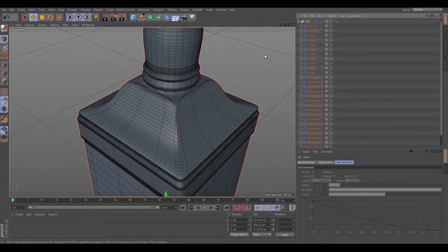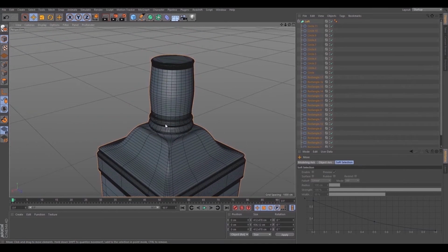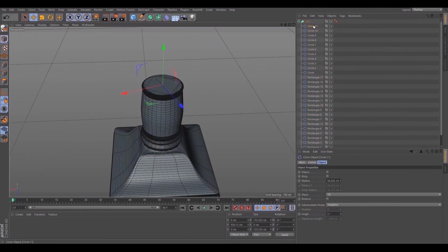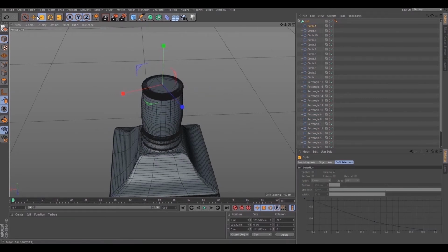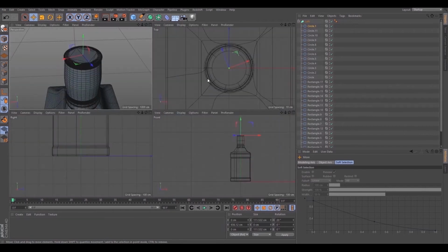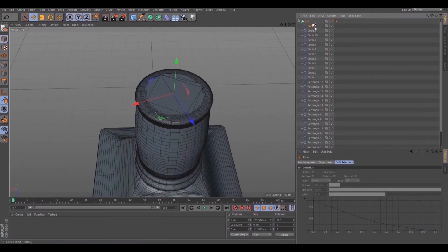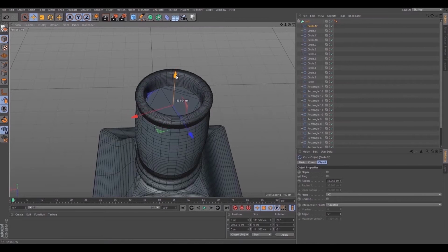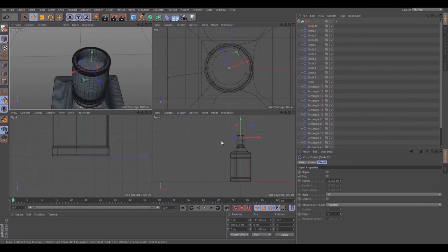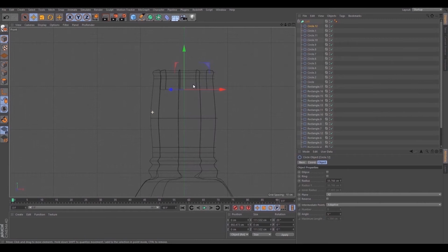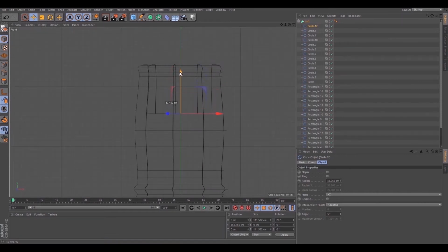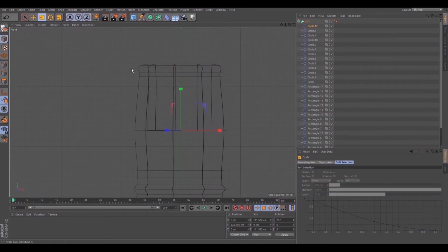Next we need to make the inner shape of the bottle. Copy this circle, scale down to the thickness of glass. New copy and move it down. Then, in front view, adjust the position with circles that form the outer shape, so that the thickness of glass stays more even in the bottle.